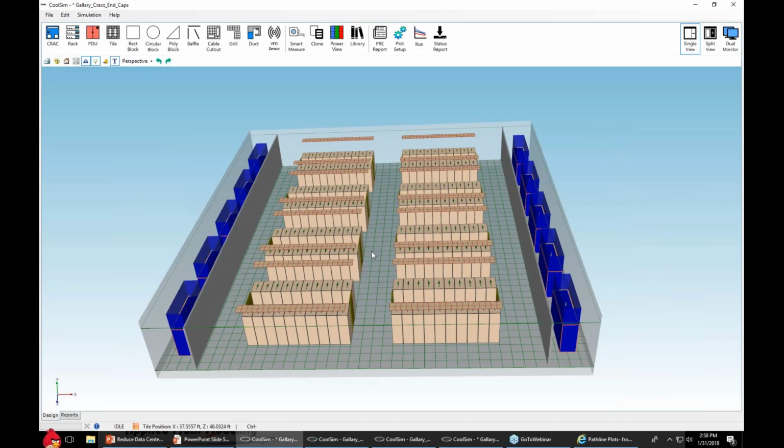with pressure. The problem is the pressure is not uniform under a floor. It tends to vary as a function of location. It varies as a function of data center design. For example, if I had all these AHUs on one side, which I have seen, and none on the other side, then you'd have big pressure variations from left to right, and on the right you'd have tremendous pressure under the floor, and on the left you would not. It would build towards the wall.